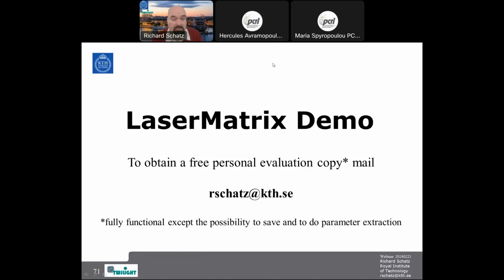In fact, there are two ways of doing it. Either you use the chirp grading function, then you are limited to certain functions, like a sinusoidal variation, quadratic variation, a polynomial variation, or exponential variation of grading, and you can do it in several sections. Otherwise, you can define your grading from scratch, layer by layer, and then tell the program to repeat this layer stack this number of times.